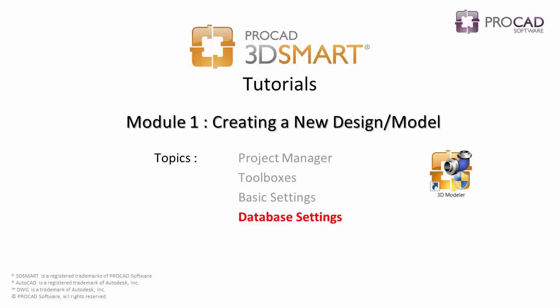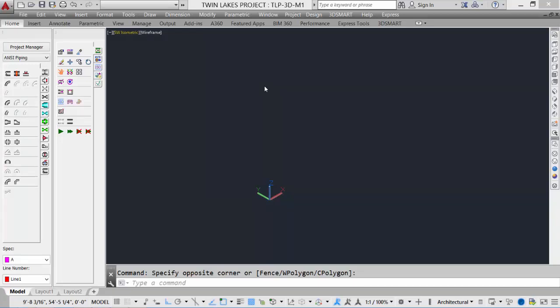Our last topic in Module 1 is database settings. 3D Smart is database driven, so there are some database tools that are accessible through the drawing environment. We select the Database Tools tab, we see three options. We can regenerate the drawing from the database, we can synchronize the database from the drawing, and we can copy a design. Regenerate a drawing from a database.